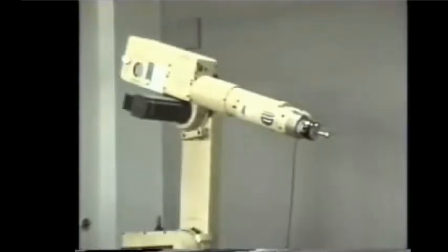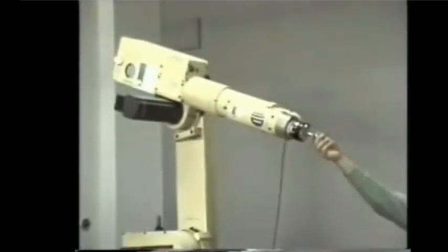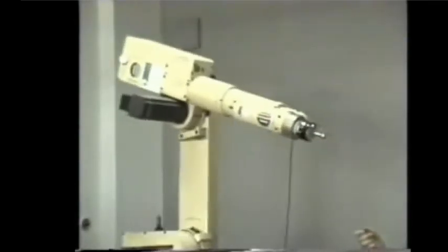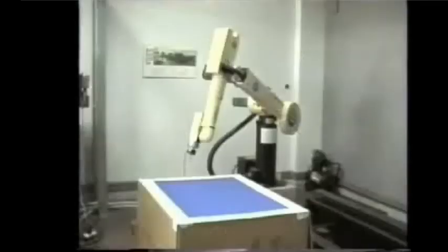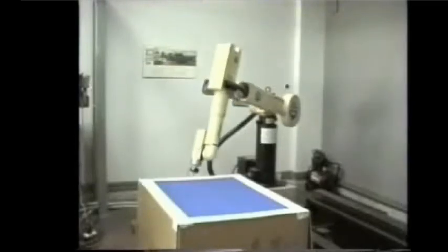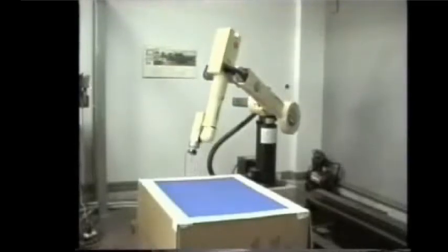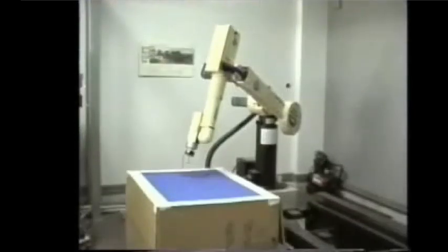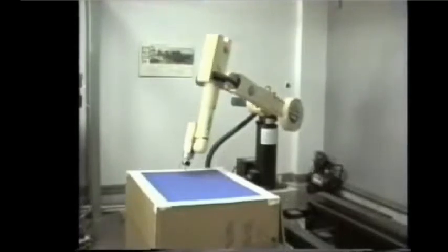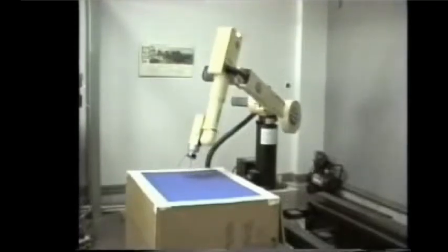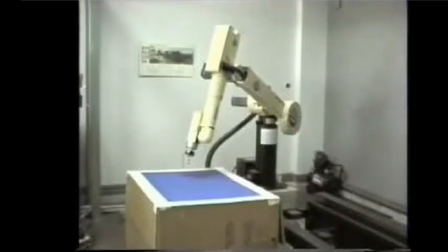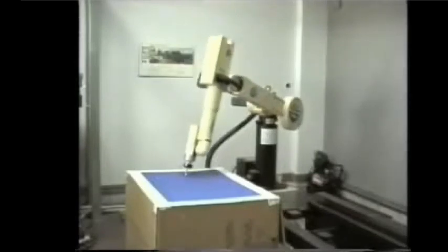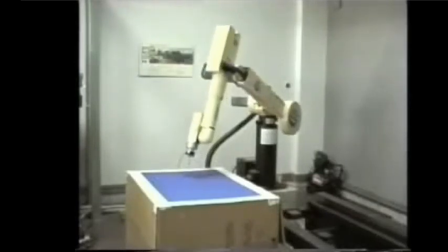Now you can also use an anisotropic choice of parameters in the various Cartesian directions, so to be very stiff or very damped in some direction and differently in another direction. And finally, the robot is now executing a circular path, but this circular path is then prevented by the presence of a box. And when you're doing this path, what happens is that you execute exactly the path in free space, and the robot becomes compliant when interacting.